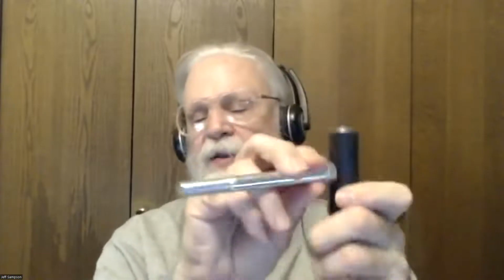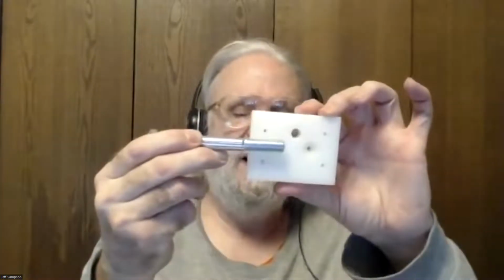I think it was on Amazon. I found those big robots that you can buy, like academic robots, for maybe $1,000 or even more than that. I noticed one of them, instead of having the type of thing you'd see on a go-kart, seemed to have what looked like a big aluminum block as their steering mechanism. So they had something that looked kind of like this, a big chunk of aluminum, with an axle screwed into the end of it like this, and a hole down through the top where you would have bearings like that.